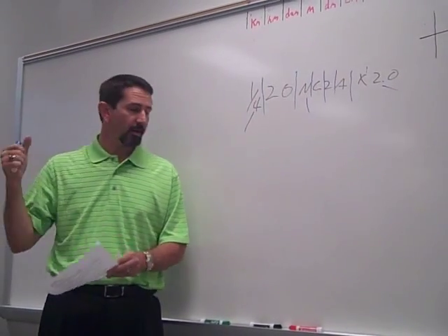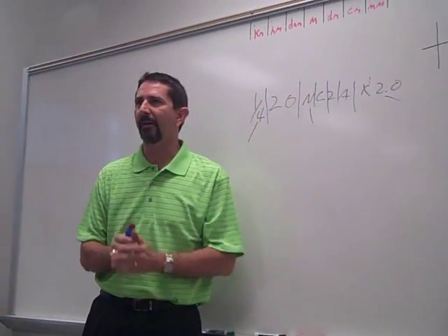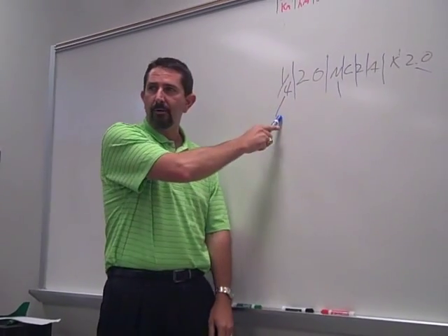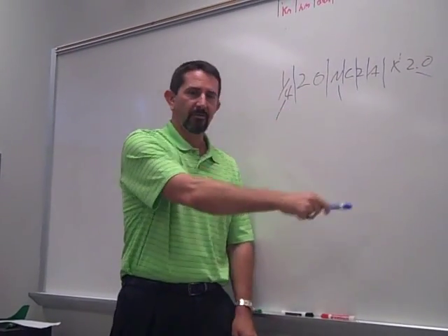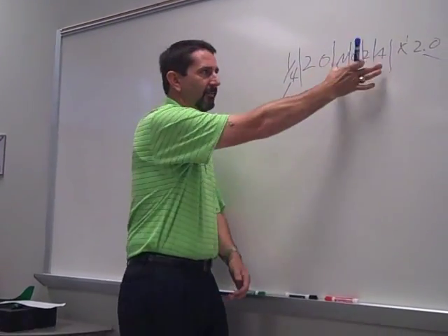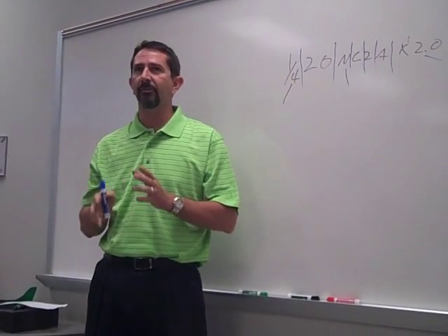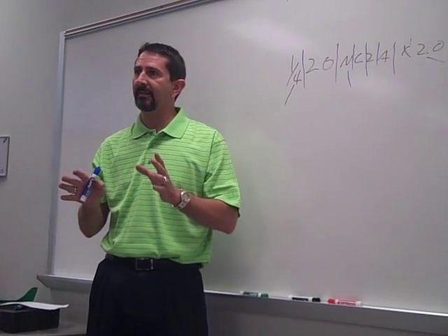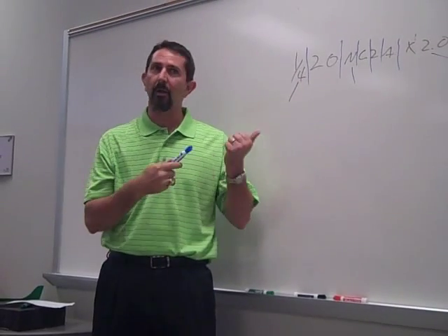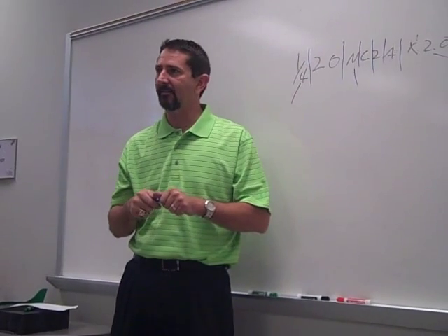Okay? So if you're going to go to a hardware store, just ignore all this stuff in the middle here for a minute. If you're going to a hardware store and you're looking for a bolt, you need to know that you need a 1/4 inch bolt, 20 threads per inch, and 2 inch length. The rest of this stuff in the middle is going to be pretty standard. There are some variations, but that has to wait, or for machinists it will be. When you go to the store to buy a bolt though, they will all be standard. Okay. That's it for symbology.